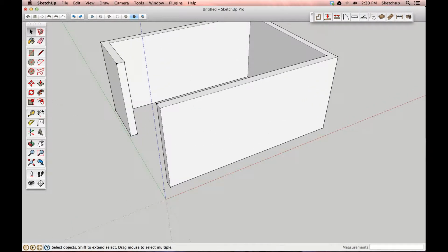Now, before I bring the window in, I could go ahead and bring up a 27-inch guideline, which is something that we're going to need. So I'll go ahead and do that. And then let's say that if I had brought over a guideline here, this will give me a place to put my window, and then we'll actually make a second one 16 inches apart.